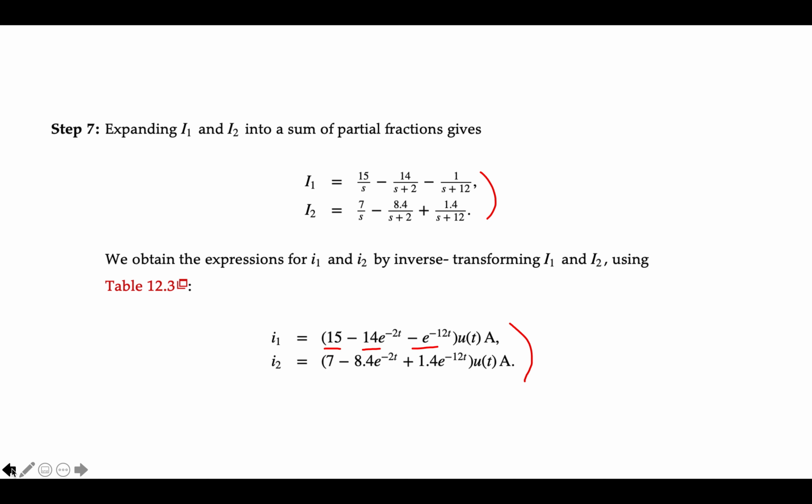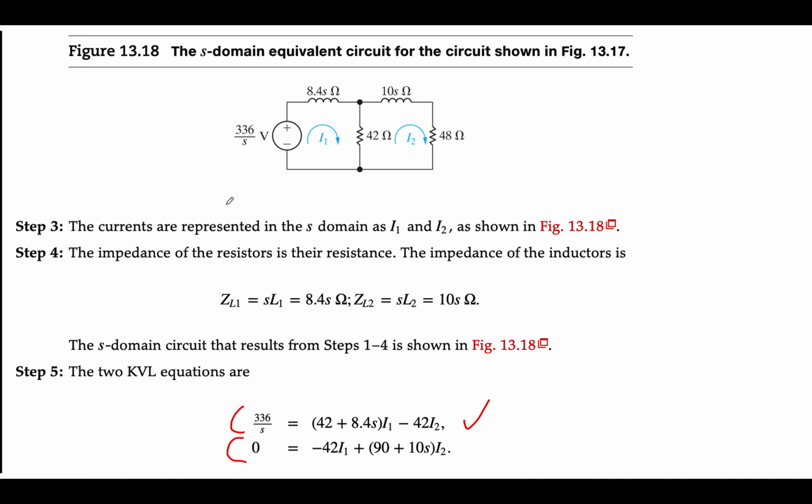So let's go back and look at our circuit. If you look at our circuit, we have two inductors, and these two inductors cannot be combined. And so, of course, in a simple RL circuit, you're going to get an exponential transient effect with a time constant, and that'll be like an L over R time constant, and that's what's going to define the natural response of the system.